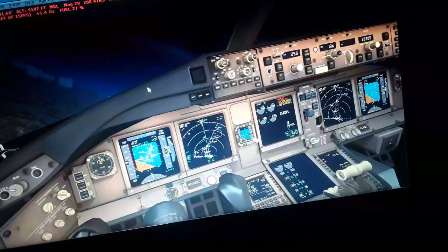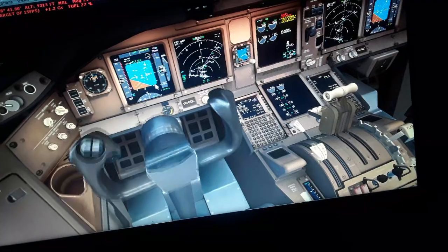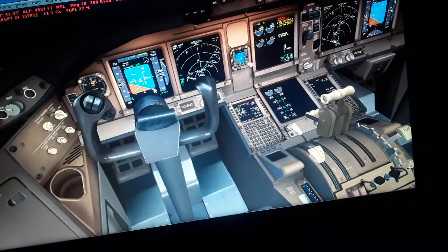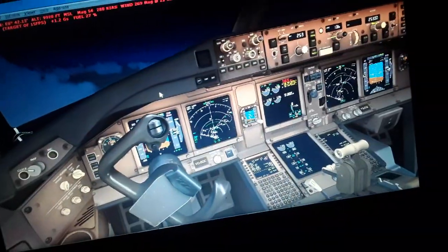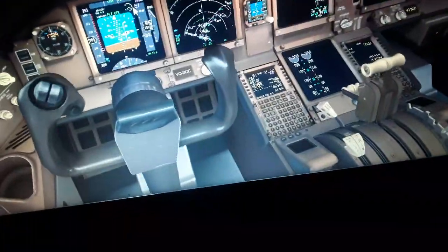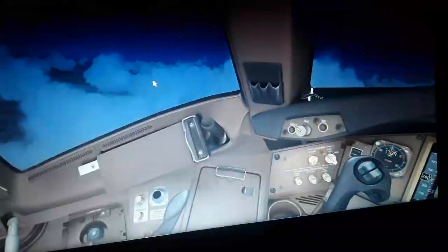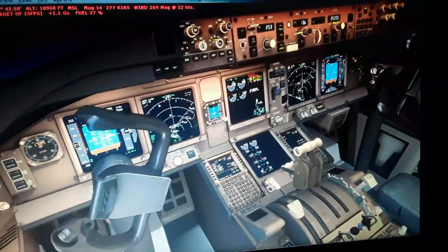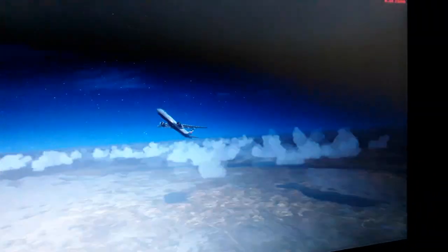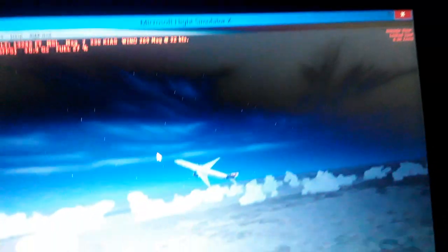You can use this, the other ones in the spoilers, and pitch up a little bit if you need. Speeds down. Also, you see the rate of climb is too much, and use the stabilizer thing. So this is the runways now. So this is as we climb out from the Zurich airport. The Boeing 777 will fly at about 500 kilometers an hour.